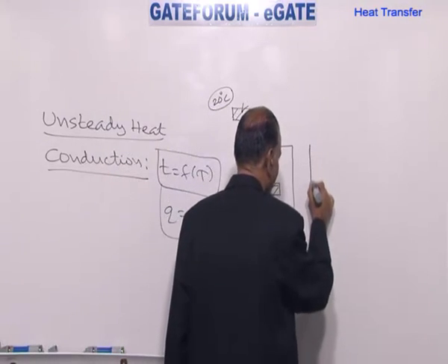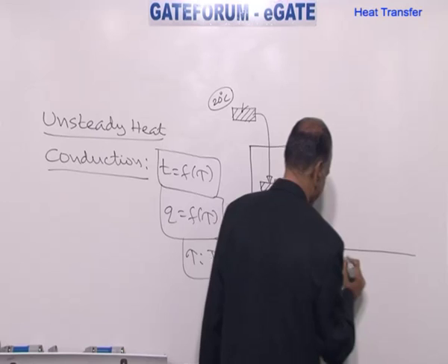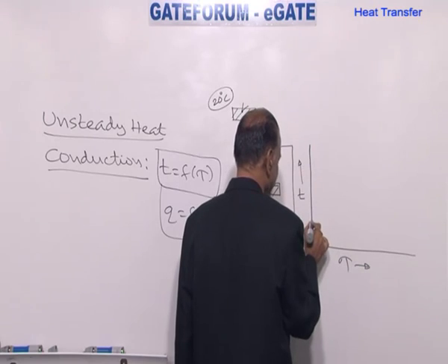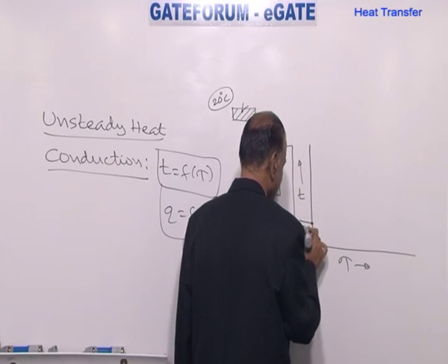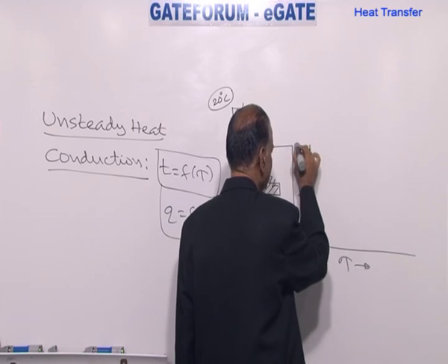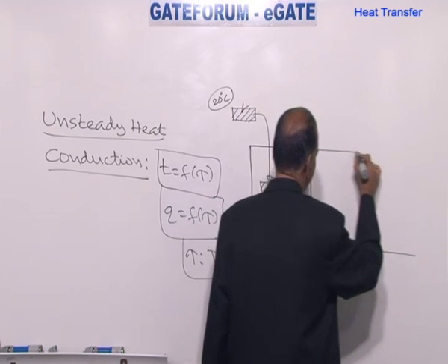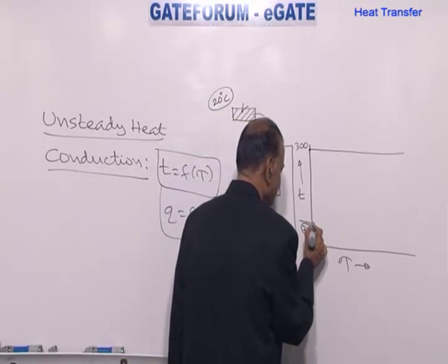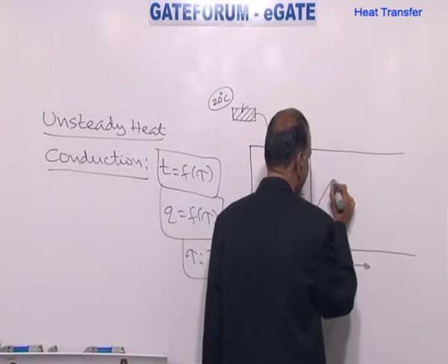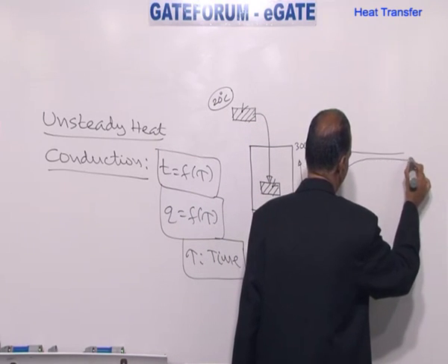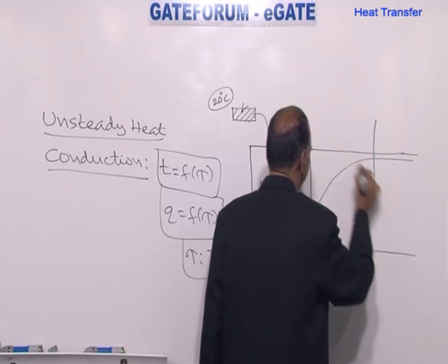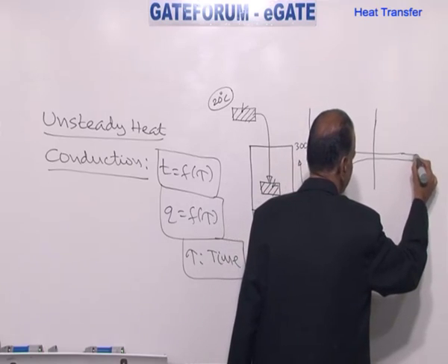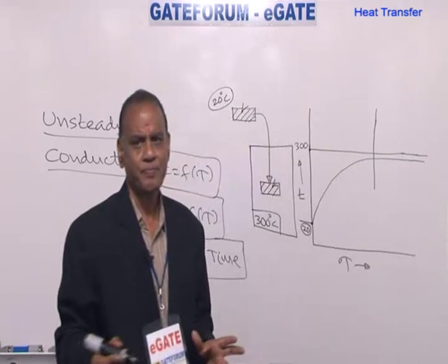And if we show this graph, x-axis we take time, y-axis we take temperature. Initially, the metallic piece is at 20 degrees centigrade. Furnace is maintained at 300 degrees centigrade all along. Then if you note the temperature, this temperature is going to rise very quickly in the beginning, very quickly. Then after some period of time, the temperature difference between the metallic piece and furnace remains more or less same.